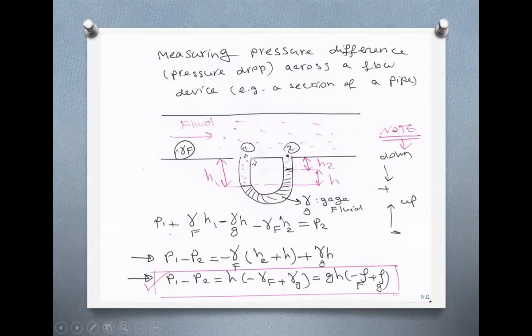So you make use of this U-tube manometer and you connect it to the 2 points where you want to measure the pressure difference. Let's say it's points 1 and 2. Inside the pipe, we are talking fluid dynamics because the fluid has motion. But within this U-tube, the fluid is stationary, so we are talking about fluid statics. So we start from point 1 and try to reach the other point in order to measure the pressure difference within the U-tube, not through the pipe, within the U-tube.